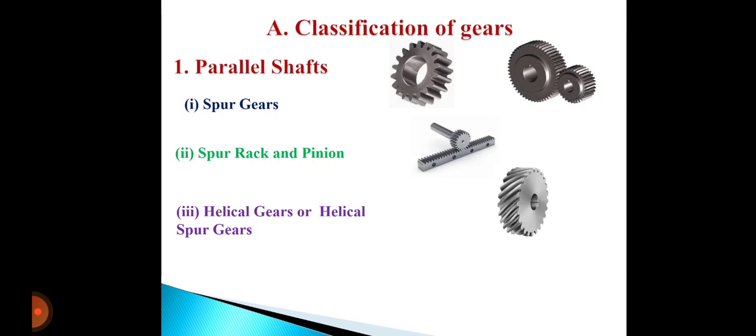at the beginning of engagement, contact occurs only at the point of the leading edge of the curved teeth. As the gears rotate, the contact extends along a diagonal line across the teeth. Thus, the load application is gradual, which results in low impact stresses and reduction in noise. Therefore, helical gears can be used at higher velocities than spur gears and have greater load carrying capacities.